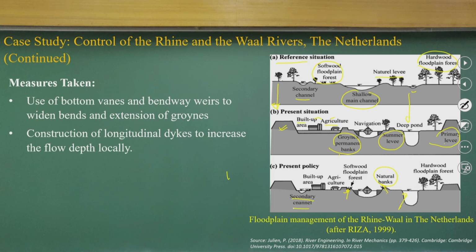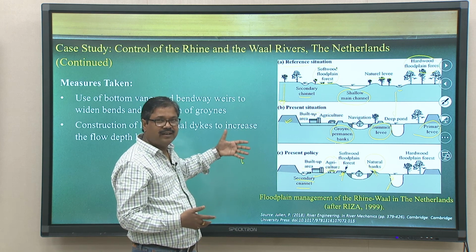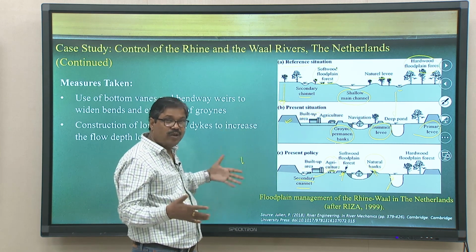Okay. That is the idea here, because you come back to the point that you can give the river its space. So the secondary channels that we closed can be activated. Whenever you have a flood, you can take a risk with these, but you want to make a natural system, because agriculture needs a nutrient supply through the secondary channels. So if you look at it, a river does not carry only water, it carries water, sediment and nutrients, and it has a space, the river corridor.